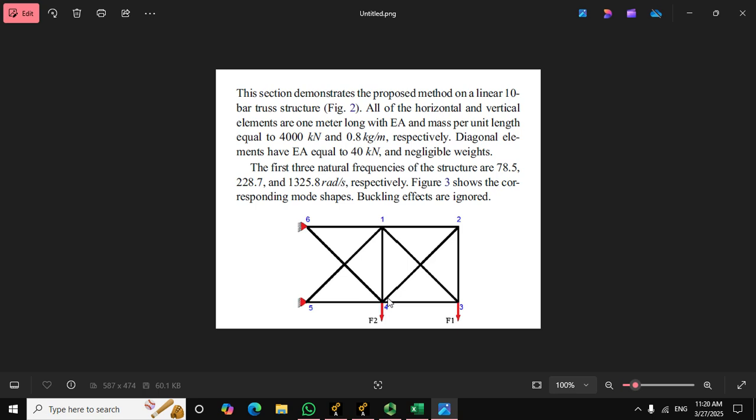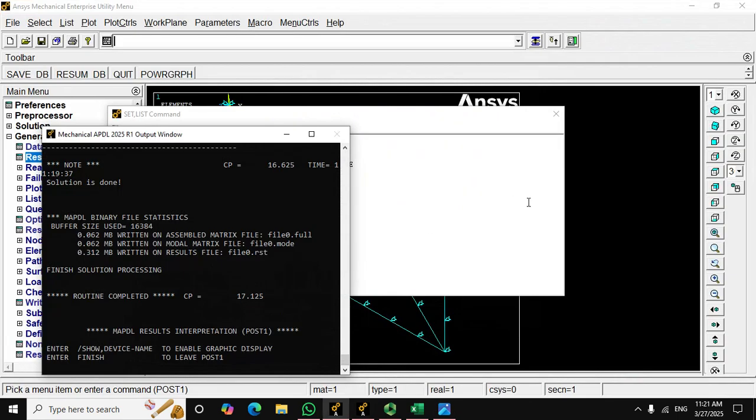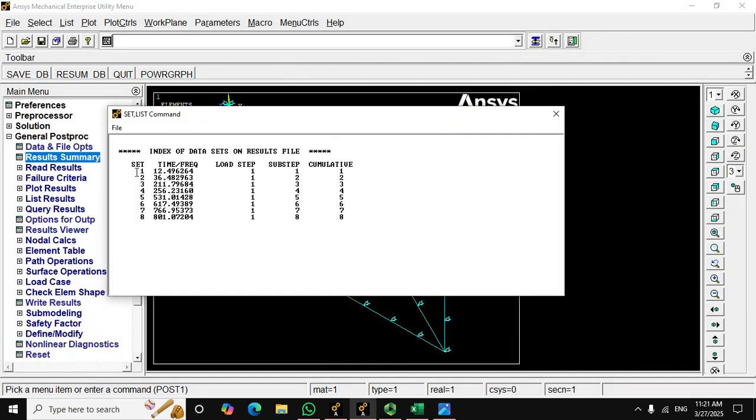On the XY plane, the degrees of freedom of these 4 nodes add up to 8, since each of them can move either in X or Y. So the total number of natural frequencies I'm gonna be able to find in 2D is 8. Remember, I constrained the movement in Z. Next I'm gonna remove that Z constraint and see what happens.